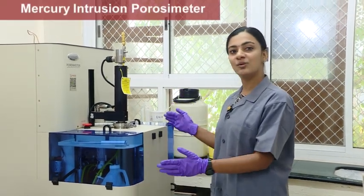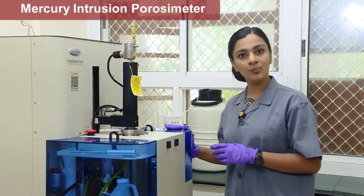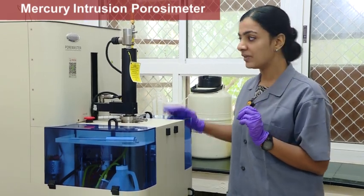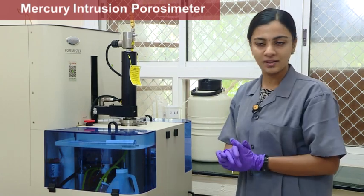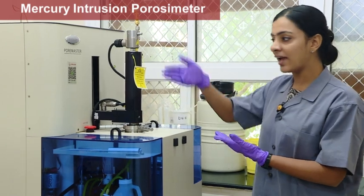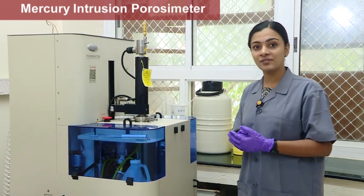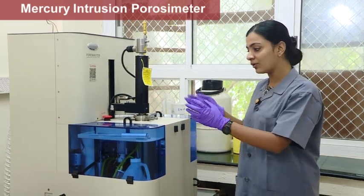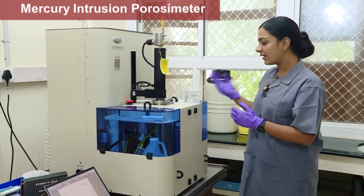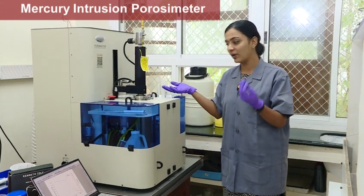So this is the mercury intrusion porosimeter. It has two chambers. One is a low pressure chamber. It has two stations, which means we can test two samples at a time. Next one is a high pressure chamber. It has also got several safety features. For example, the LP chamber and the HP chamber, both are independent. Another major feature is that it is a bench top equipment and the mercury transfer from LP to HP is at the bench level. And also we have LED readouts which show the pressure at every point in the low pressure chamber.